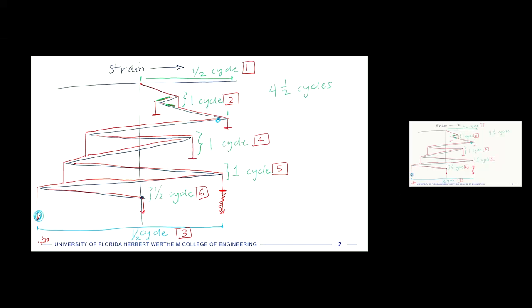And so what you would then do is use your S-N curves and stress-strain curves, and potentially the stress-strain curves for cyclic loading. You would have all of these as your database that you were drawing from, and you would program an algorithm to count all of these cycles.